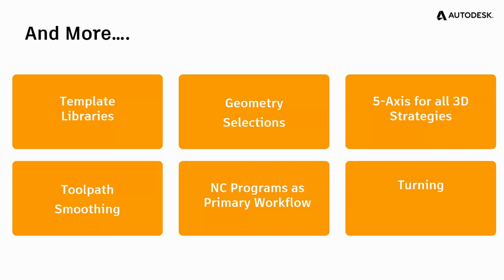We're also working to include more 5-axis programming capabilities for more 3D strategies. Now, these are the appropriate strategies where you might choose to run them in a 5-axis mode. So this is initially going to be limited to ball nose or hemispherical cutting tools, but who knows in future how this might evolve. We're also continuing to improve the quality of our toolpaths to make them smoother. And this is using things like more even point spacing within the toolpath itself, which is ideally suited to running on older machines where randomly distributed points can result in a very jerky machine motion.